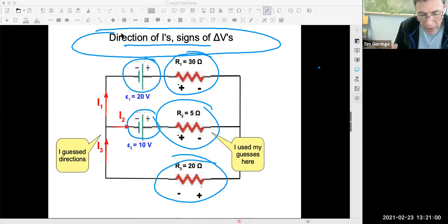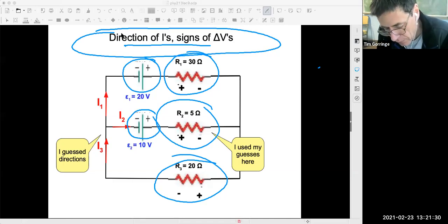So my currents, we always draw in circuit diagrams as conventional currents, the direction that positive charges would flow in. That's the direction of the current. It may or may not be electrons in a circuit, but it doesn't matter whether it is or is not electrons. We always draw the currents in the direction that positive charges will flow. And so they always flow down the electrical potential hill. Okay, so these are the signs.